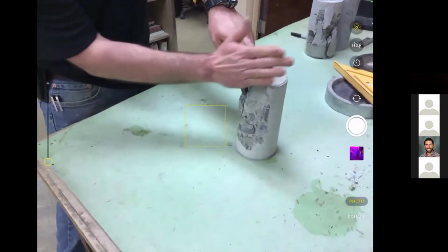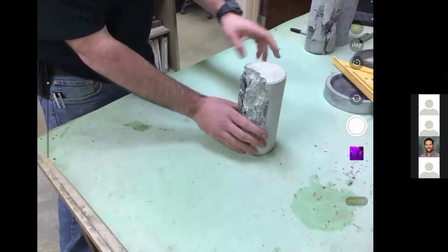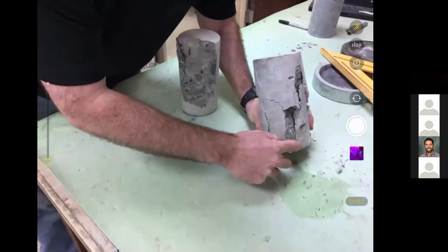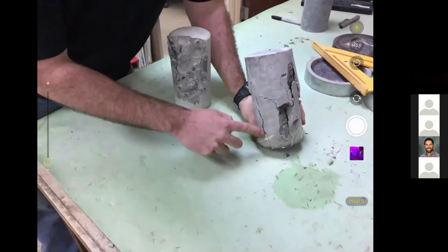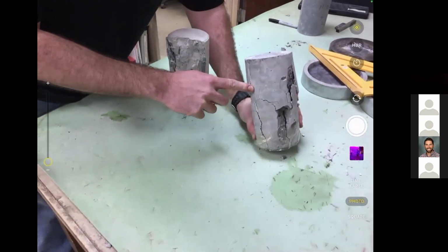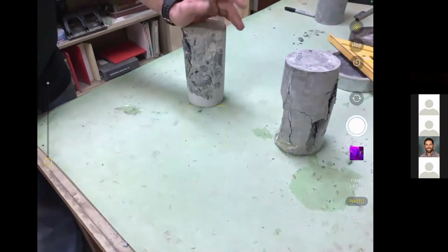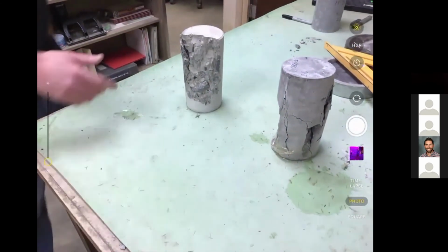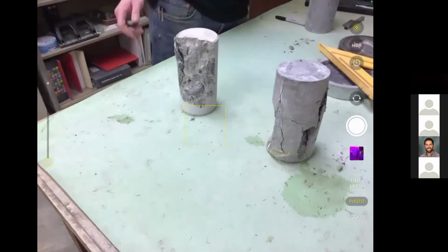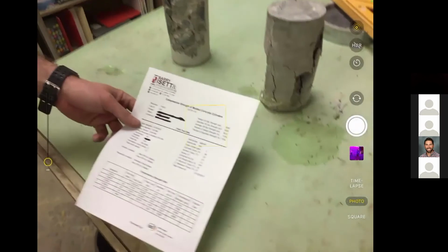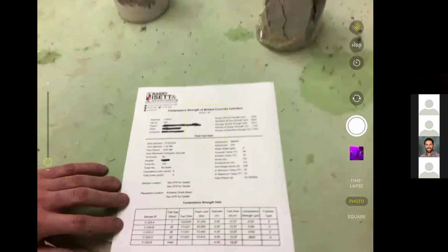This just basically shears off on a side. Your type 3, on the other hand, has these vertical cracks running through it. These are your 2 most common that we will find, okay? And then once that's done and we get the breaks done, we enter it into our Geosystems database, and every week we'll print out and send to your projects a printout of the compressive strength.